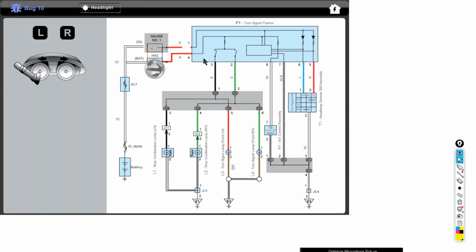Now, you look, I've unplugged it right here, the bulb goes out. So that means the wire between the fuse box and the turn flasher is good. It's not shorted to ground because there's no longer a path to ground. Plug that back in. And at this point, we can continue. So we know it's on the right side, again, since the left side is like that.